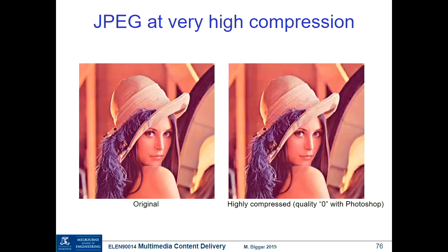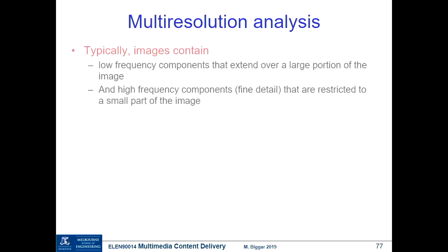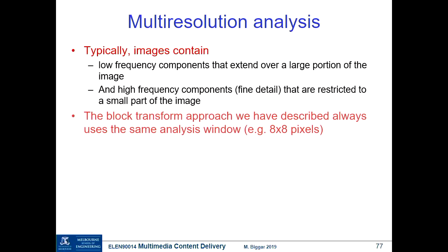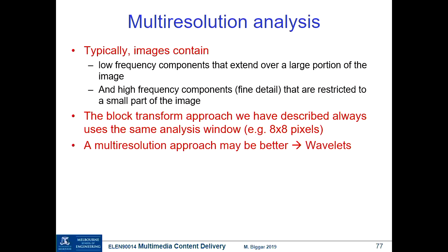And yet the block-based structure, the 8x8 pixel structure, always uses the same analysis window, right? It always looks for frequencies within that same block size. So that was why it was considered that maybe a multi-resolution approach might be better, and led them to look at wavelets.